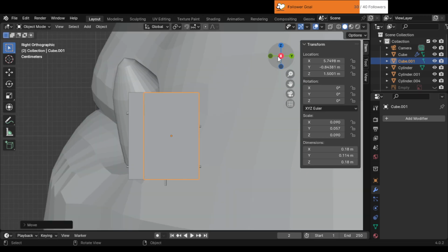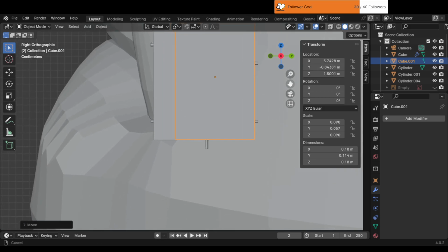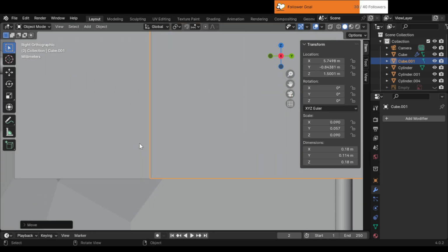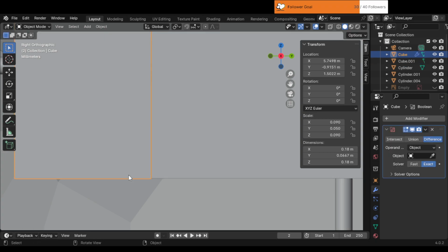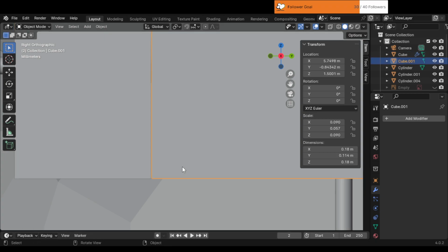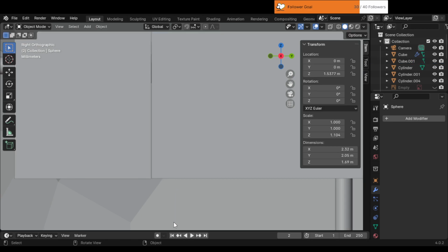Export. When you are ready, select the container mesh, your mold, and export it to an appropriate 3D printing file format, such as STL. Conclusion. Once you have successfully created a mold using Boolean operations in Blender, you can 3D print it later. Make sure to check your mesh and export settings to ensure the mold is prepared correctly for printing. You may want to review the final mesh for any potential problems that could affect the 3D printing process.